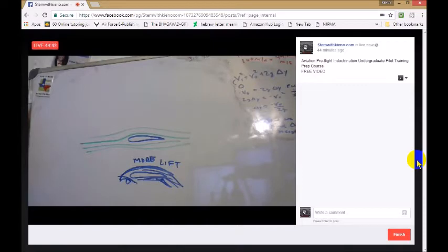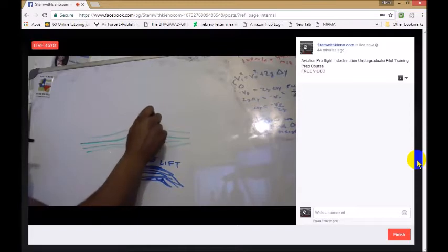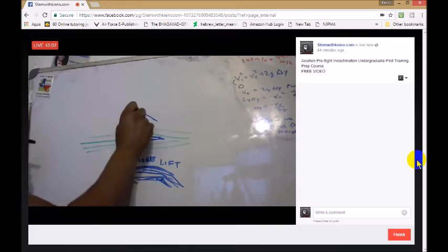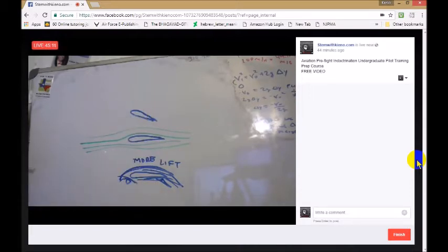Whereas in this clean configuration, we don't have as much camber, and in a sense we're producing less lift at slower airspeeds. So this airfoil at a low speed, compared to this airfoil at a low speed, is producing more lift. And this airfoil, with the flaps and slats retracted, would have to be pitched slightly more nose up in order to generate the same amount of lift.